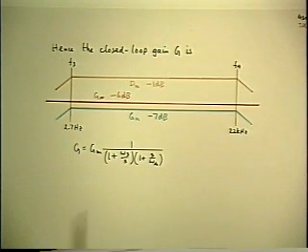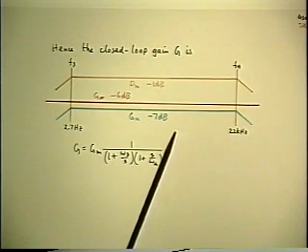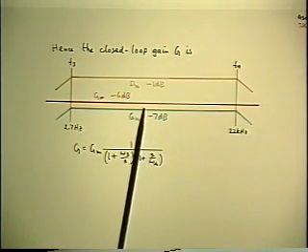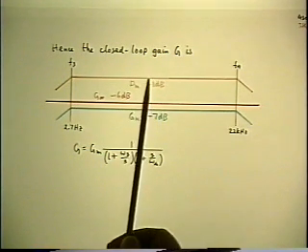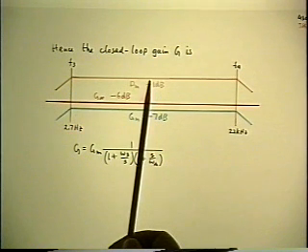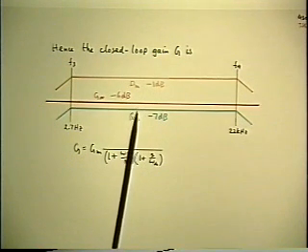I've purposely chosen numbers that make this rather a poor amplifier, just so you can illustrate the relationships. And the deviation, even at best, is 1 dB away from the ideal value or the specification, because the mid-band loop gain wasn't that high anyway. It was only 20 dB. So Tm over 1 plus Tm is 10 over 11. So that's 10% less than 1, which is why you get a 1 dB discrepancy.